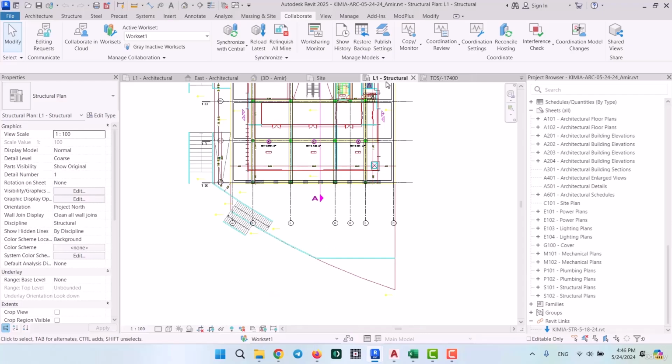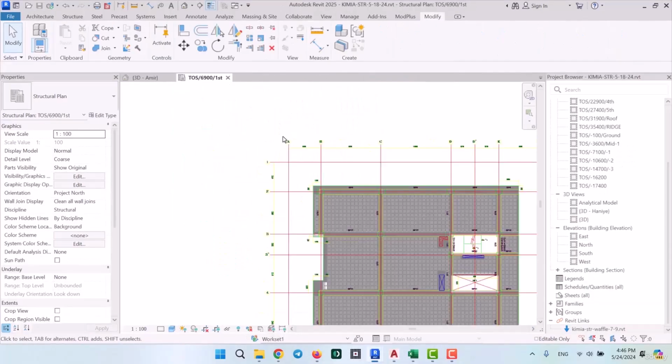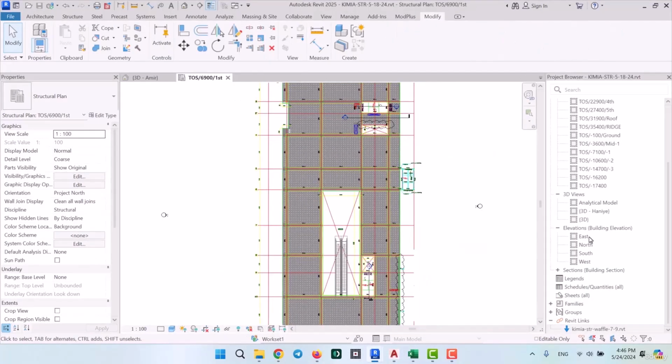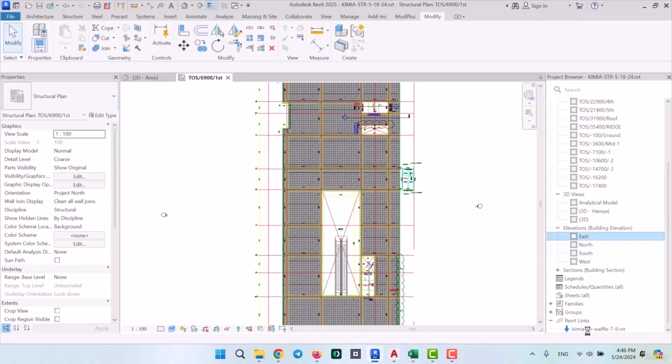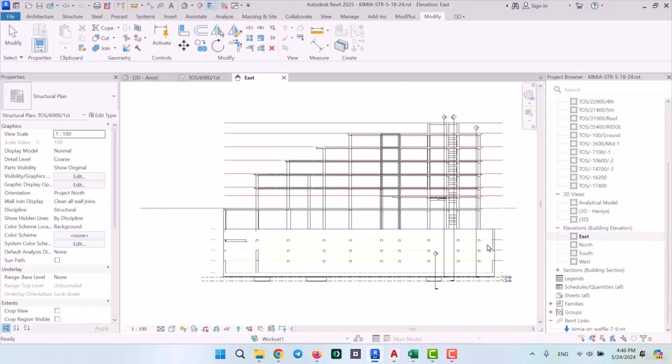Also, if you notice that you have missed some things, then that's because those items were definitely not inside the workset that you've closed. You're going to have to go over here and open the structural file and check to see what the problem was that doesn't make these items show. It's either because of their worksets, or maybe they're part of the linked files here, and stuff like that. Now let's go check this out together.